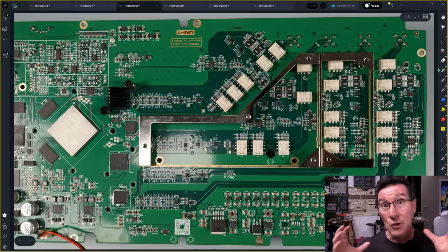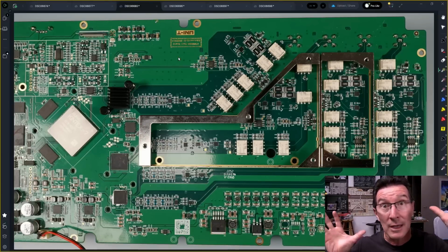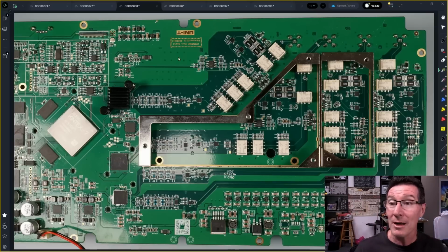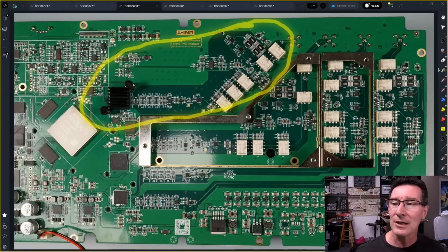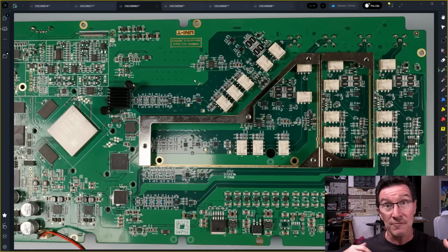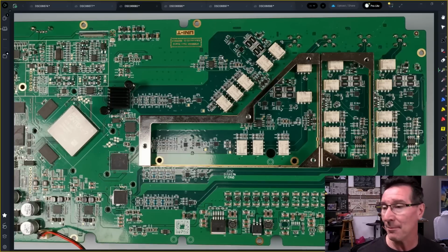So when you're talking about something with a low impedance source, then it's really difficult to have external interference, like external EMI, coming in and disturbing that circuit because it's very low impedance, whereas all the stuff coming in is very high impedance, so it doesn't really disturb it. So you don't really need any shielding on a low impedance circuit like this as far as external influence coming in. You might need it if you don't want it to radiate stuff, but that's a different aspect to actually being shielded to protect it from any outside interference.